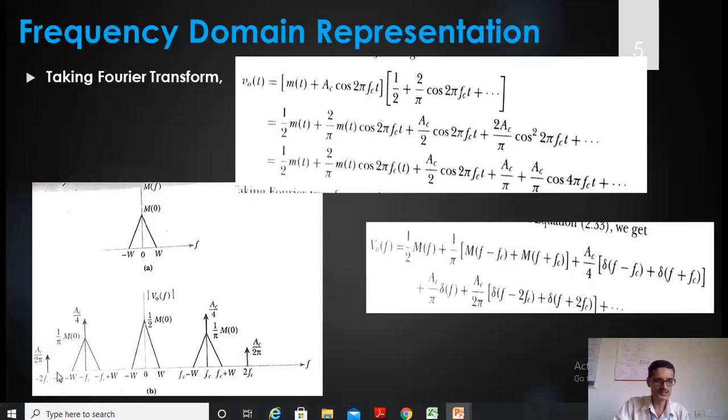Now what I will do is, I design a band pass filter which is used to allow only this component. So this is the ideal characteristic of, say, band pass filter. So I will draw one band pass filter characteristic curve over here, which is used to allow only this component. Okay, that is 2 sidebands and 1 carrier, unmodulated carrier. So hence we get a conventional AM signal by using switching modulator.